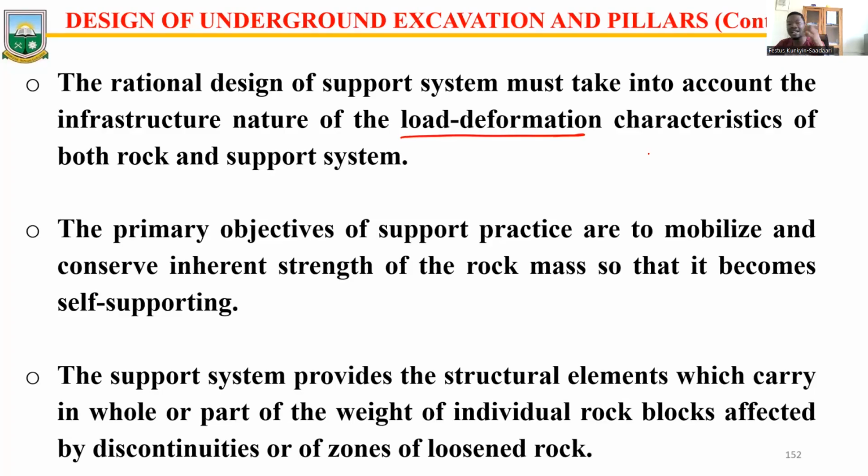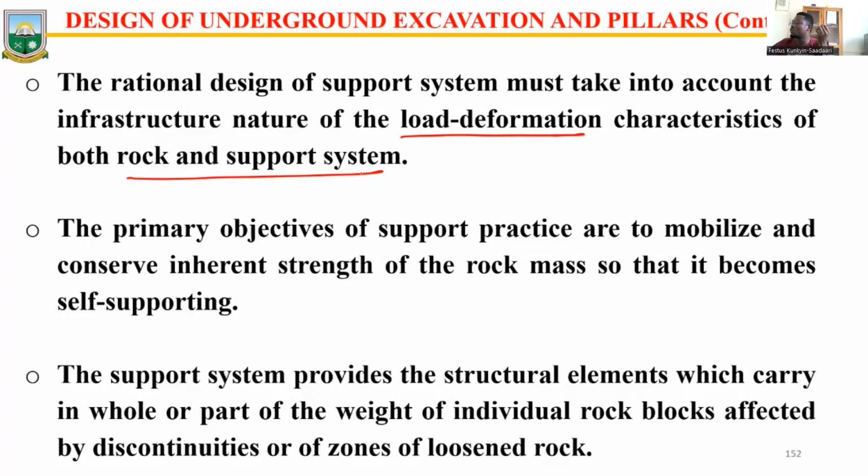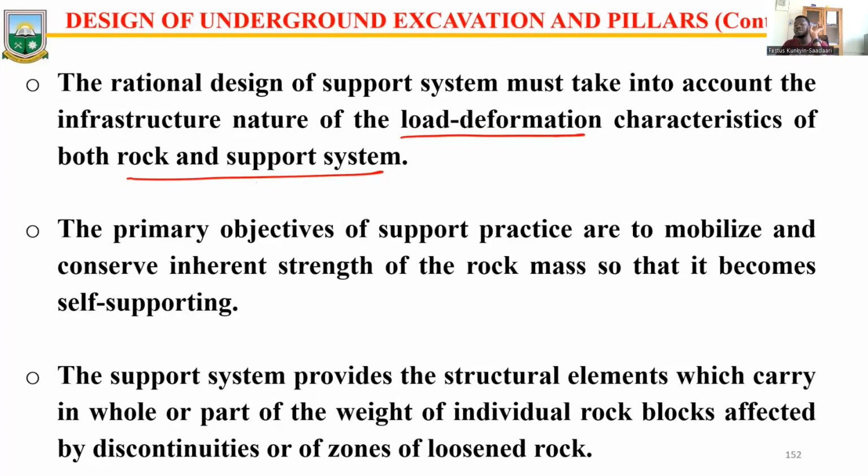When I understand them, then what can I use as the support? The type of material I'm going to use as the support, I also have to understand the properties and characteristics that surround this support system. If I understand the material the support is going to carry, then I'll be able to tell whether I should use wood, steel, concrete, or even rock bolting. Will it do the action? So I have to understand this.